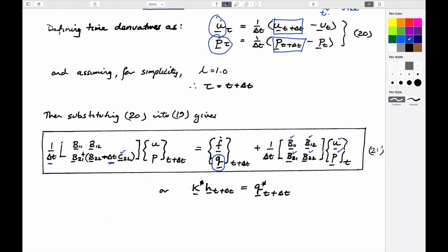But the one thing that maybe is a little strange here is what the boundary condition would be if we applied it onto the top of an element. The boundary condition is that we have to apply a force, but we're interested in how that force changes as a function of time. So if you apply a load and you plotted that load versus time, and this is time 0, this is the first time step, this is delta t, this is 2 delta t,